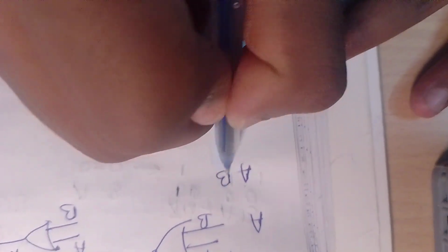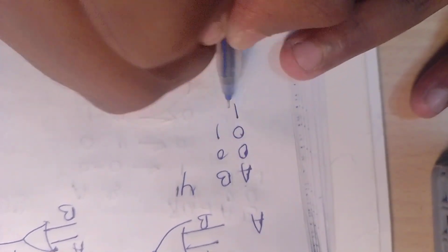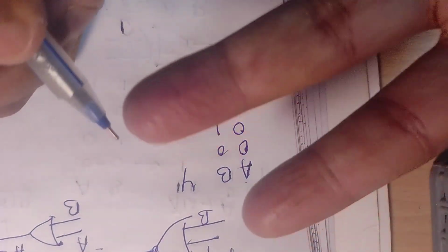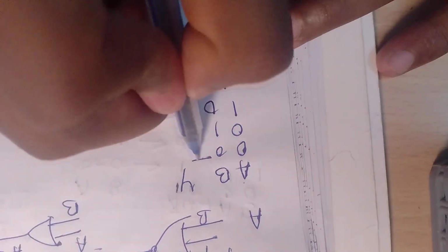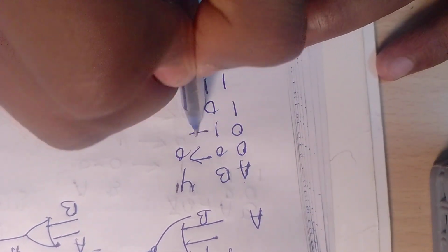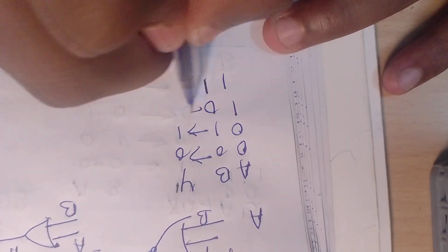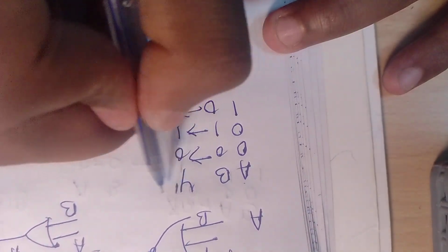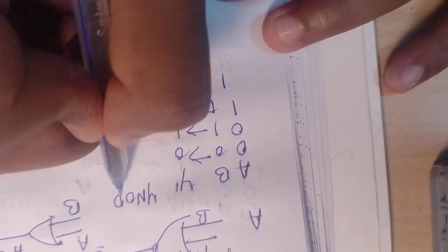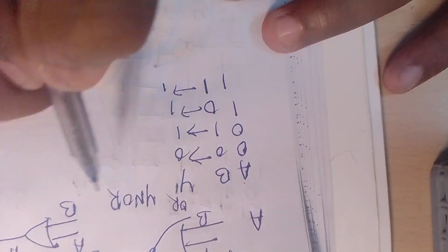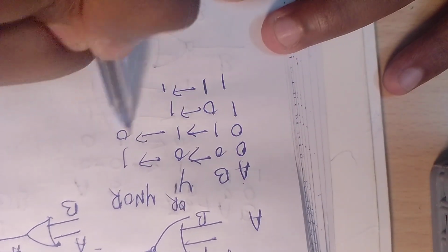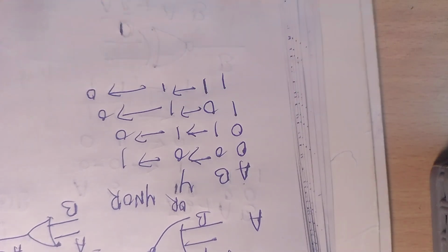If you provide A B and Y as 0 0, 0 1, 1 0, 1 1, as I already said, 2 switches means 4 combinations. So for the OR operation, 0 1 1 1, and Y of NOR is the inversion of that. If you want to disable this gate, you can provide the control input as 1.